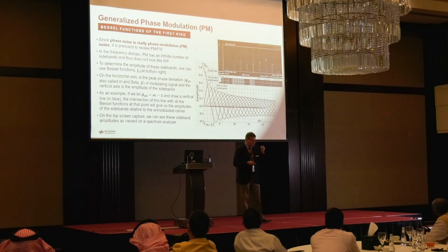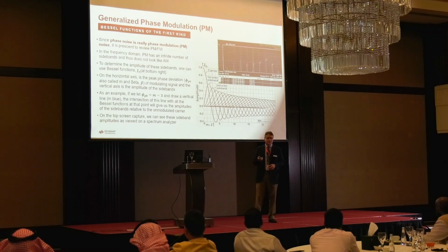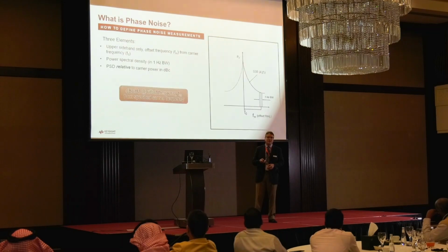Now, in the case of phase noise, remember it's a random effect, right? It's generated by thermal effects on the physical characteristics of transistors or other components in my oscillator or my device under test. So we actually have an infinite number of Bessel functions, and as a result, what we start to see is our noise skirts that I showed on the prior slide here.